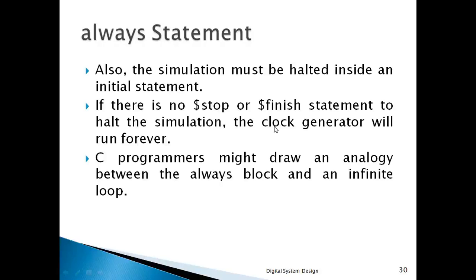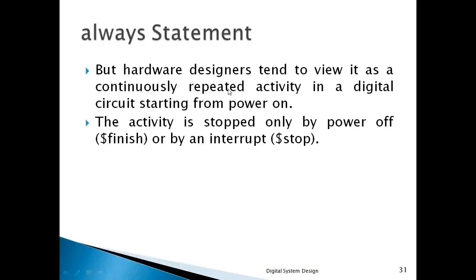Now if we make an analogy between the always block and an infinite loop, it is the same: the always block works like an infinite loop. From the hardware designer's perspective, it is the same as continuously repeated activity in a digital circuit starting from power on.